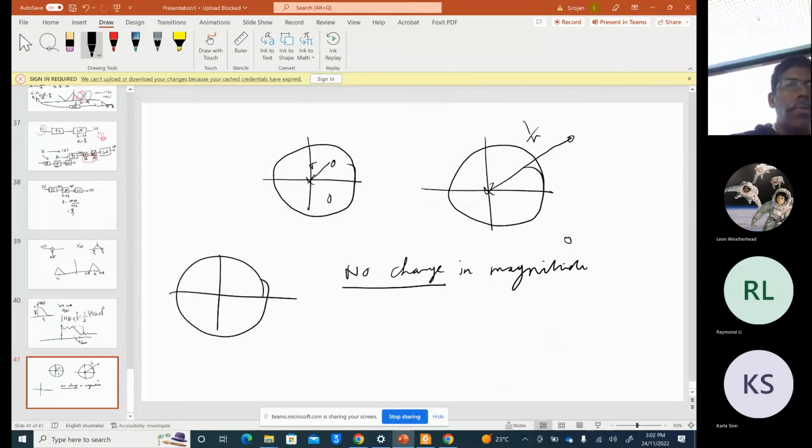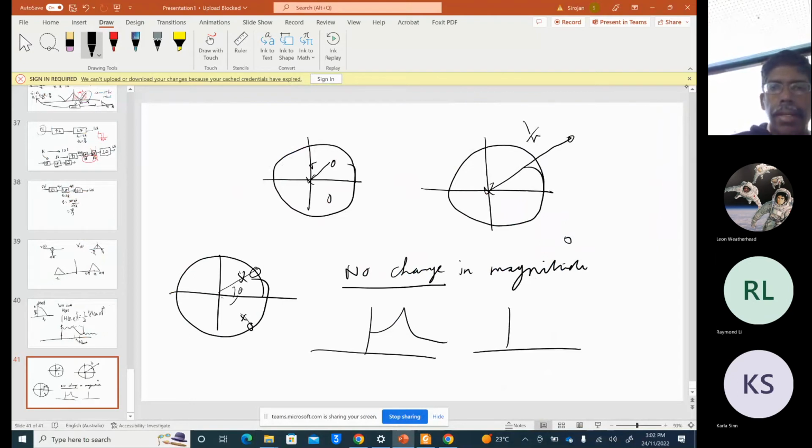When you have these two poles, your filter becomes a peak there. But when you put these zeros here on the same theta angle, then at that point the frequency is taken out. So that is the notch.